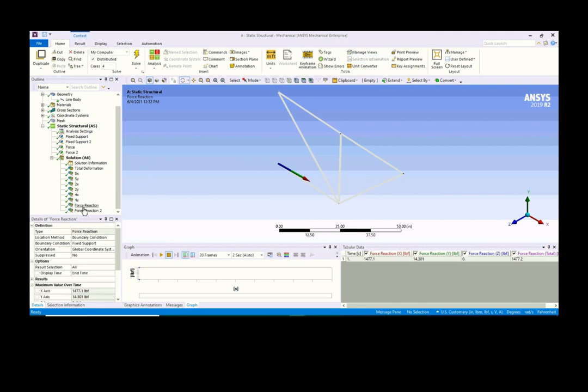So you can find out that what we had just now is around 1500 for node 1. Going in this direction, this is around 1477.1. The reason there is some y force reaction is because ANSYS's solution is using iterative methods. Also, what we calculated just now is mainly translation in the x and y directions.